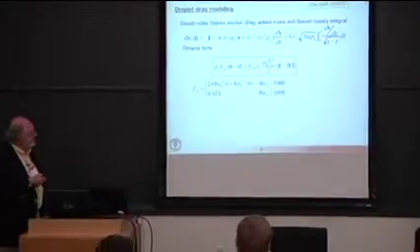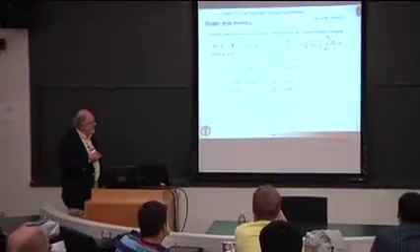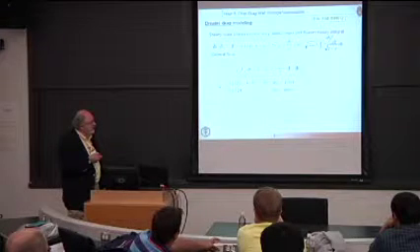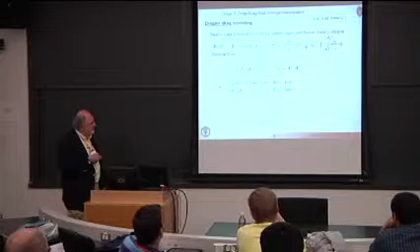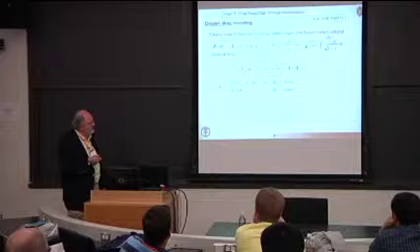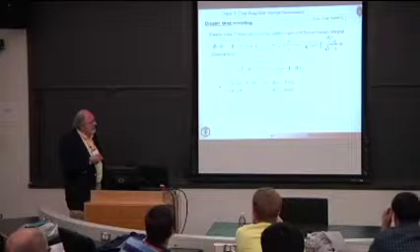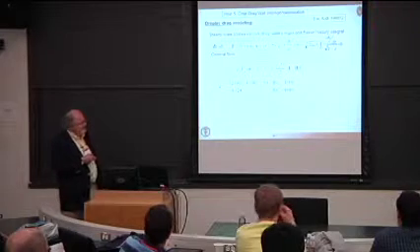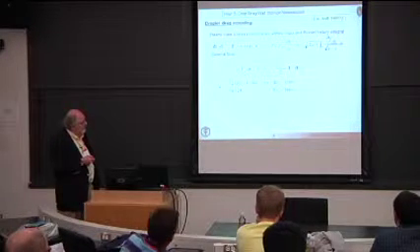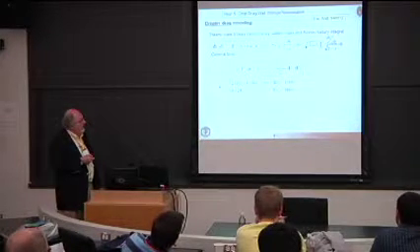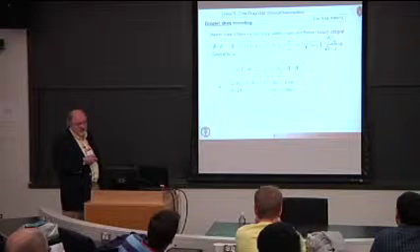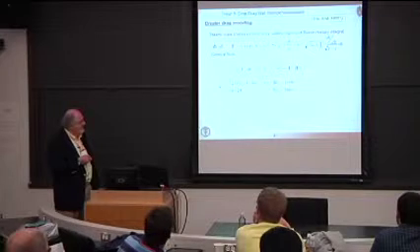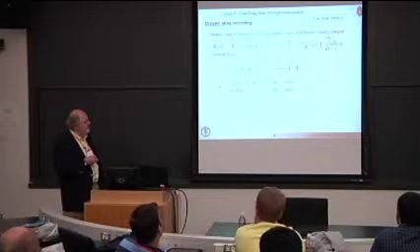And in fact, what is typically done is the equation is written in this form, where we have the liquid drop density times the volume of the drop, so this is the mass of the drop, times the acceleration, equals a force. The force is the dynamic pressure, the gas density times the relative velocity between the drop and the gas, u squared here, times the frontal area of the drop. So if it's flattened, we'll see that that's affected, as is the drop drag coefficient.